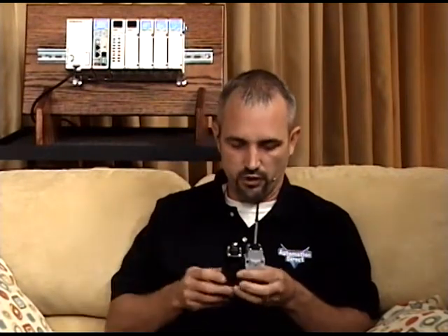Now these all come with contacts. I believe they come with normally open contacts. You can buy them normally closed. You can buy doubles. The contacts are adjustable, because I used to get the question of, well, how far does the lever actually have to travel before the contact makes? Well, there's a set screw inside. You can adjust it up or down, so it's a little less sensitive, a little bit more sensitive. If you want different types of arms, maybe a broken arm, you can buy arms and whatnot. And Tom's going to go check that out real quick.